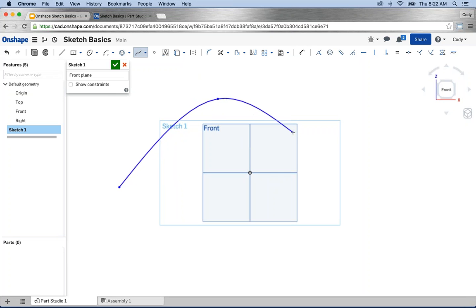Useful in a number of different situations where you need these types of shapes, and it's not easily created with simple lines, arcs, and rectangles, and so on. But you're really defined by the number of points. So just some tips. With splines in general, the fewer points you have, the better. In many cases, splines are just 2 points or 2 or 3 points. They're not very complex.